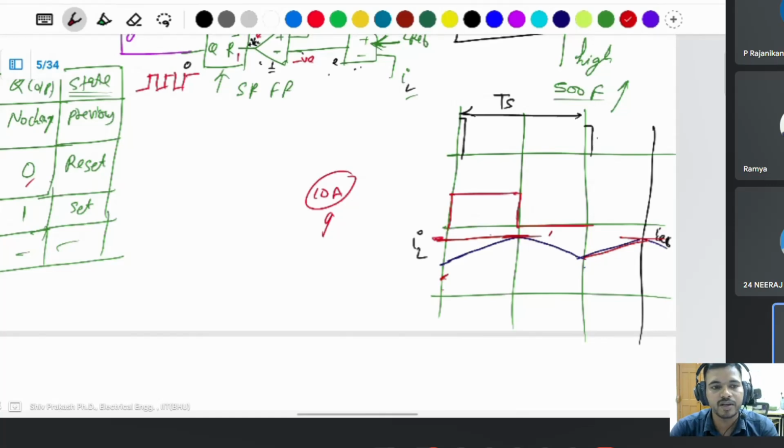That's why in PWM, you know about the DC-DC converter, there is a use of the sawtooth waveform in place of the triangular waveform as the carrier wave. In all systems, a carrier wave is used to generate a PWM in any electrical circuit. To generate the PWM, you use a simple triangular wave or sawtooth wave. Triangular wave is used in all systems, but in a DC converter it uses the sawtooth waveform because of this only.